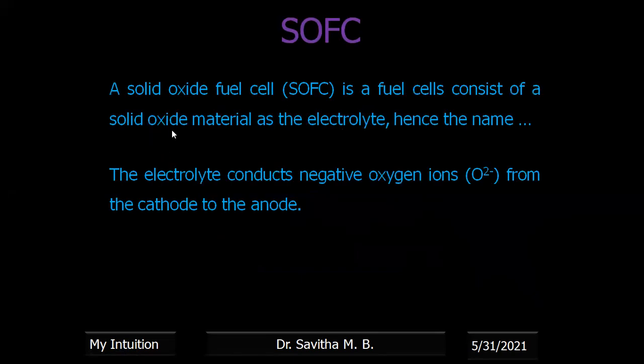So, the solid oxide fuel cell is abbreviated as SOFC. Now, this consists of a solid material as the electrolyte. Hence, it is called a solid oxide fuel cell. This is a recent innovation in fuel cells. In all the previous fuel cells, the electrolyte taken is in the form of a liquid. As we know, using a liquid as an electrolyte has a lot of limitations like leaking and corrosion. But the recent innovation is that instead of a liquid electrolyte, a solid material or matrix is taken as the electrolyte. It will perform the same function.